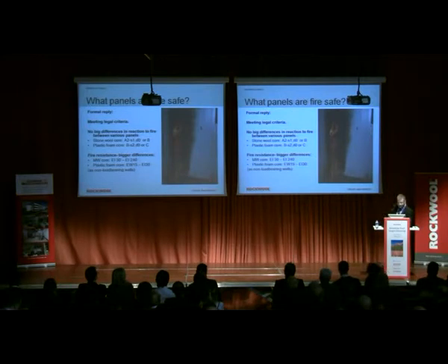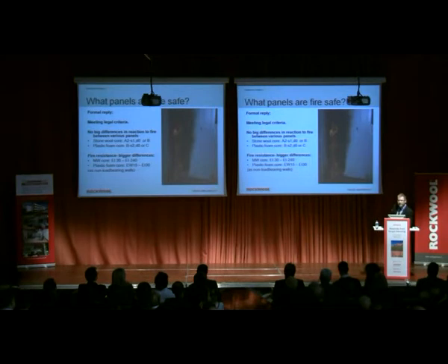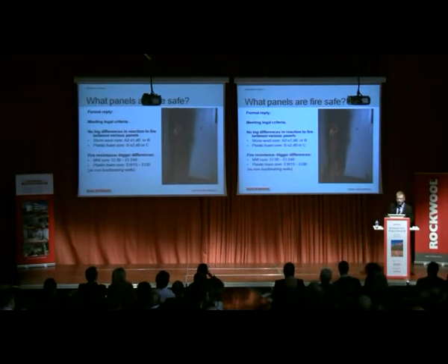If you look at fire resistance, there are bigger differences. With stone wool core sandwich panels, you can have at least 30 minutes, you can have as long as 6 hours. With using combustible infill like polyurethane or PIR, you can achieve from 15 minutes to 30, sometimes even 60 minutes. It's important to mention that this is not for sandwich panels, this is for walls made of sandwich panels as a complete construction.